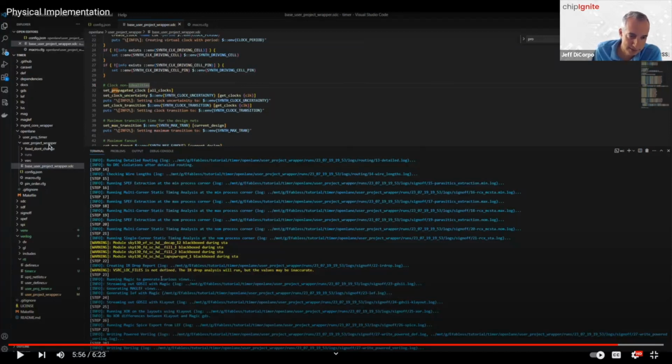And you cannot change the top level instantiation of that macro. Depending on how you implement your design, you can flatten it and just run everything at that level macro, or you can, as in this example, implement a sub macro that hardens your logic separately and then gets routed or implemented in the top level in a separate step. If you do the latter, you're going to run each of those macros separately, starting with your sub macro and then finishing with the top level macro.